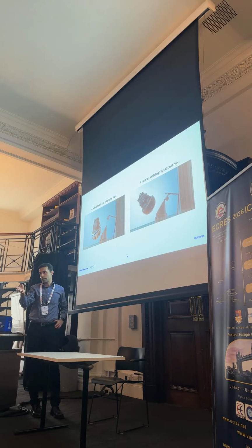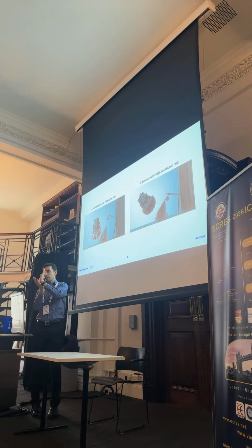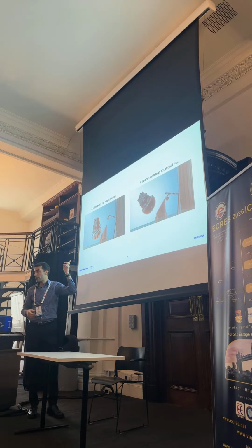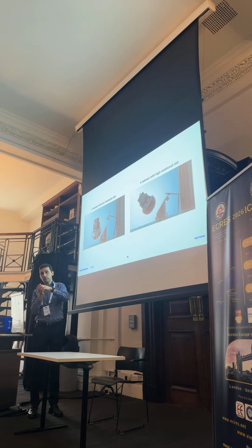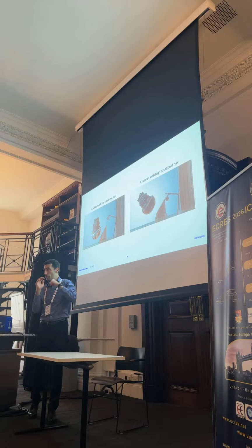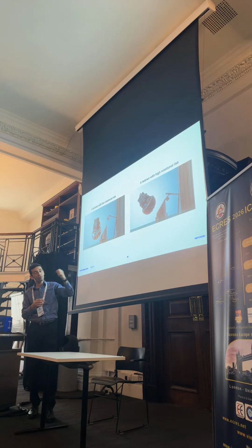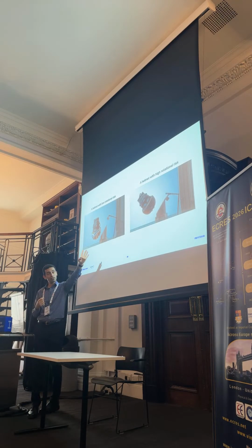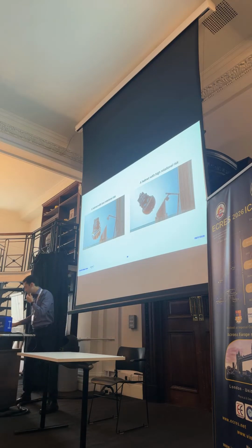And that's because of the helmet. You see the helmet here is sliding on the head. There is a slip layer within the helmet, this yellow layer, maybe you've heard of it, it's called MIPS. That kind of disengages the head from the helmet's rotation, allows the helmet to rotate, but it can prevent the head rotation quite a lot, as you can see here. But that helmet is coupled really tightly with the head, so it doesn't really allow much helmet rotation. And as a result, there is a lot of rotation of the head. And if you look at the risk of rotation, obviously it is much bigger in that.